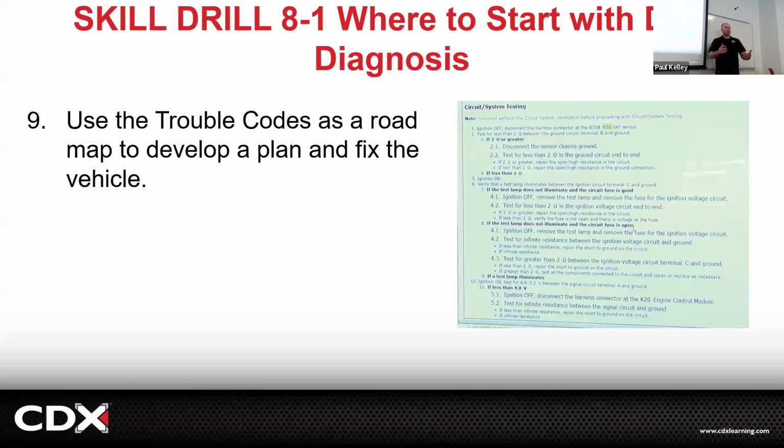So these flow charts kind of walk you through the diagnosis, right? But to be honest, as a real professional technician, you should already kind of know what the flow chart is going to have you do, but it's good to follow the flow chart. You follow the flow chart, perform this, yes or no, do this, in spec or out of spec, do this. Was the result good or bad, right? It will guide you through it.